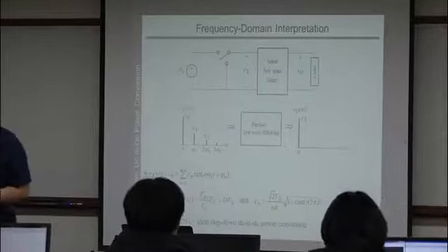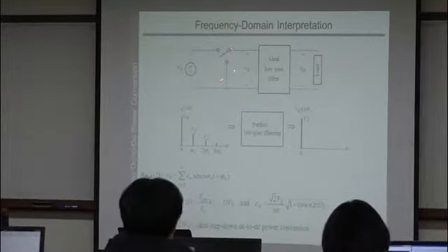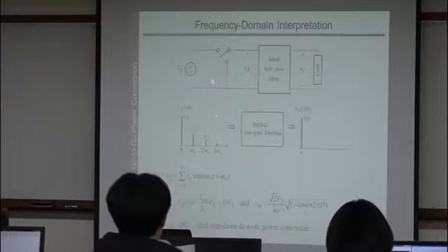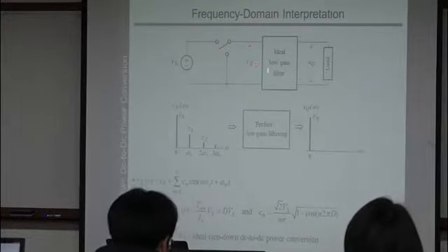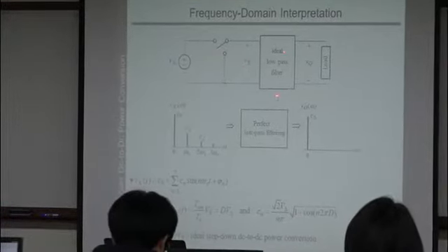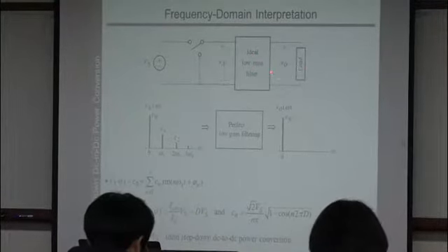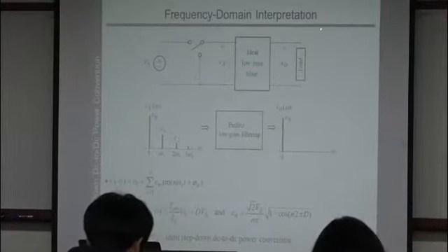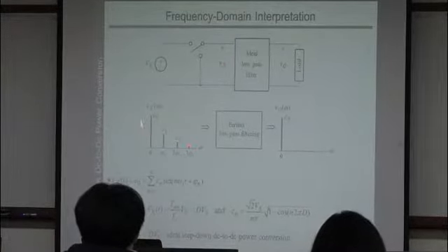So we have discussed this circuit, this structure, last time. We have a single pole double throw switch, and the Vx is a PWM waveform. By passing it through an ideal low pass filter, you can get the Vo, that is a DC voltage. And in fact, the Vx includes this component.